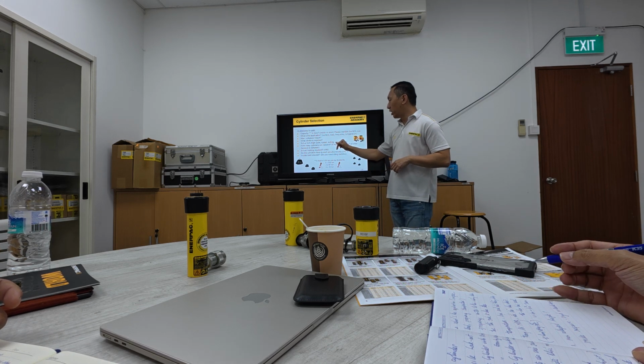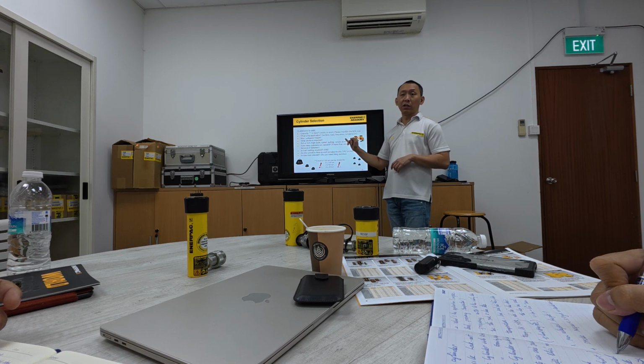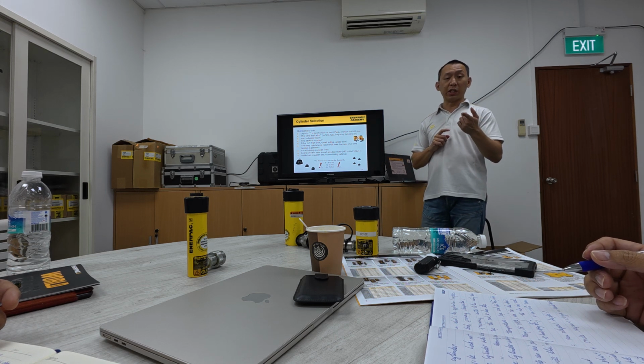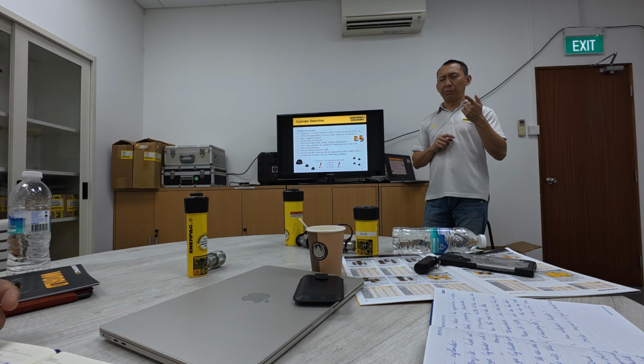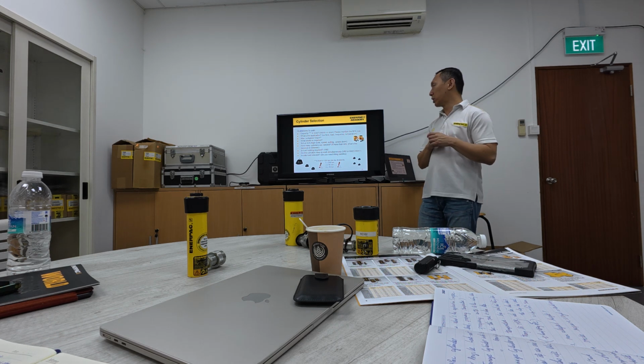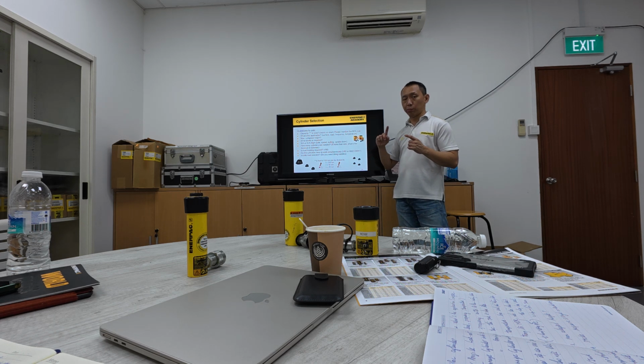Okay, next, pulling. If it's a pulling application, definitely double acting, not single acting. Unless you use the single acting full cylinder, the BRP cylinder. We have this full cylinder series. Okay, so check whether it is pulling or pushing in your application.